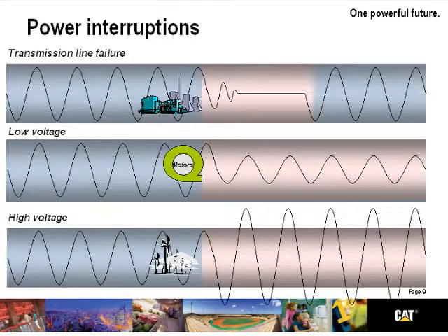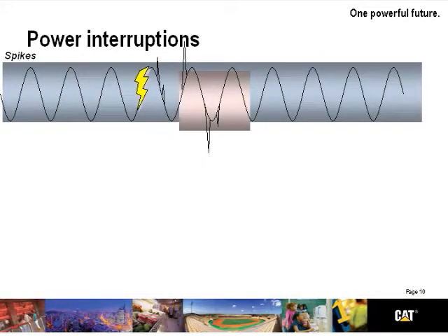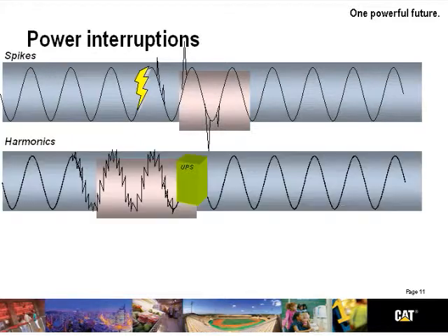High voltage? What about when people turn motors off? Or we see compressors that get turned off, and all of a sudden there's an extra availability of power. We will oftentimes see high voltage situations there. That can also happen when the utilities place extra capacity on the line, driving the voltage up almost instantaneously. Spikes often happen. The biggest culprit, of course, lightning. As a lightning strike happens near your house, many of us have lost electronic components. That's pretty normal. That's why we need TVSS, transient voltage surge suppression, as well as UPS in our facilities.